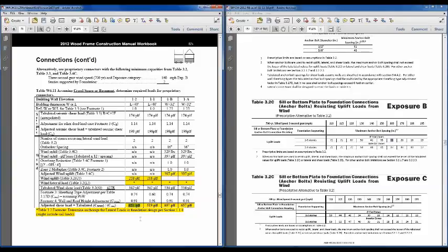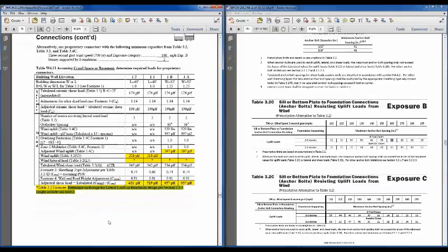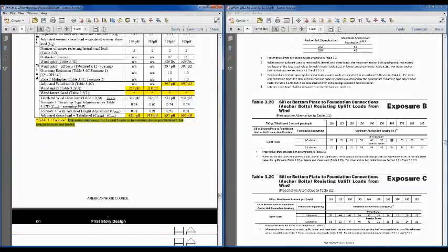Want to just make mention of this row here that doesn't show a lateral load calculated for this basement or this system. And so this footnote at the bottom is the reason for that. The lateral loads, since those might include soil loads, are not shown here. So we could calculate lateral loads, but you're probably going to have to do a soils analysis to design that basement system anyway, and so we don't show those lateral loads in this particular one.